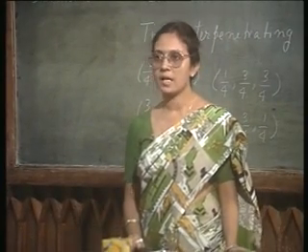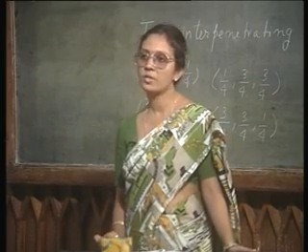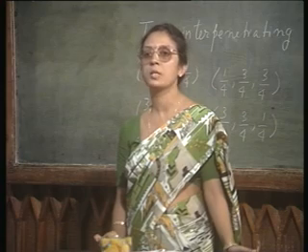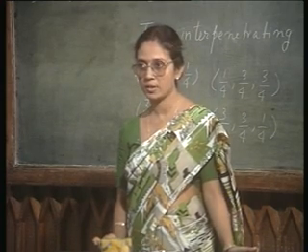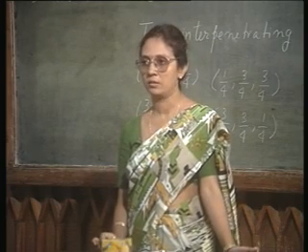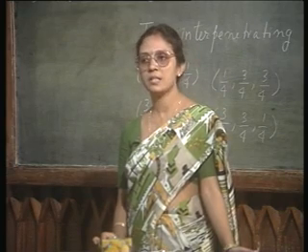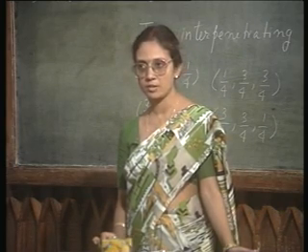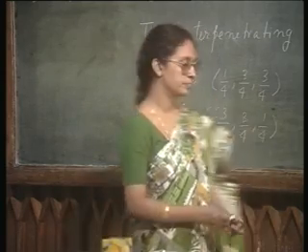When I say it is a diamond lattice, what I mean is that there is no difference between the two sublattices, they are made of identical elements. In this particular case, both the sublattices are comprised of silicon. So, silicon is a degenerate form of zinc blende structure, which is called the diamond crystal structure.